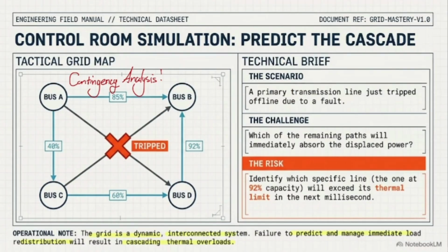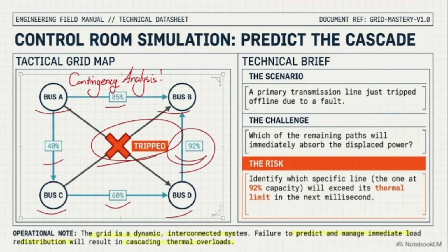Imagine that your system goes from bus A to D, and then we are going to have some trips. While all of them are connected, we put in the trip. At this point, almost everything is normal. But as you can see, the thermal loading between these two sections is going to be higher and higher. At some points, they can handle 210% or 233% of their normal capacity.